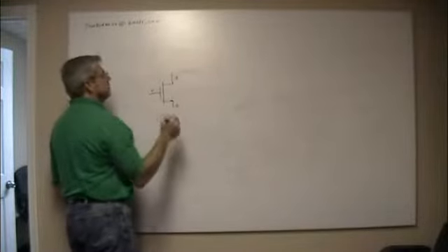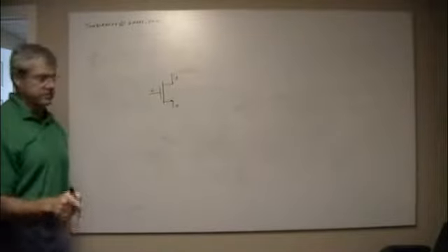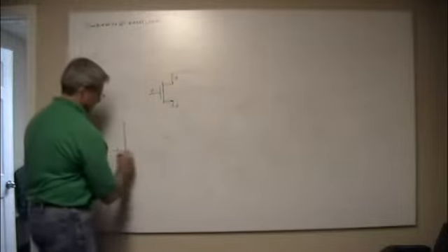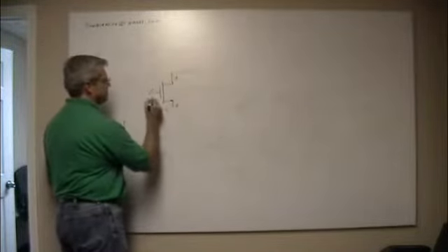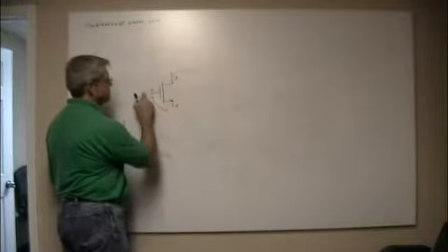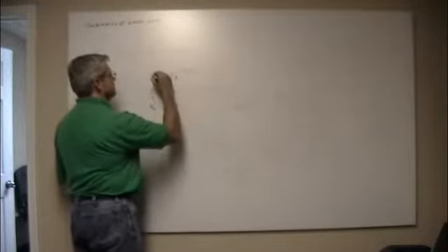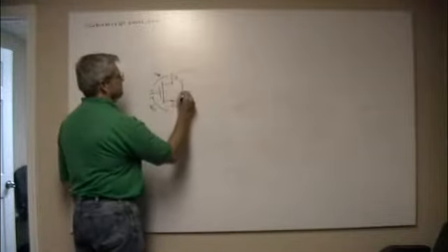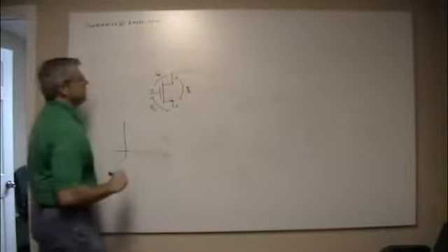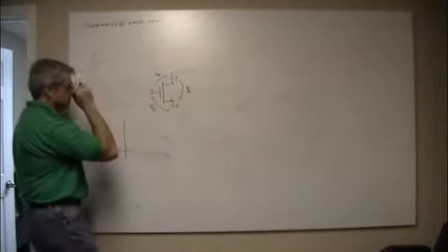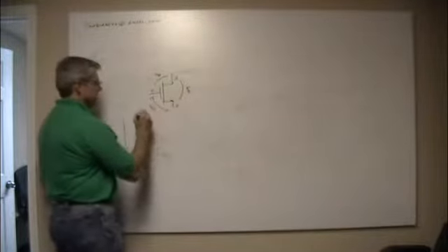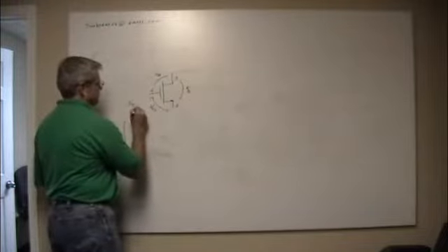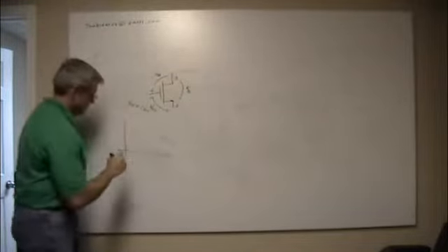And in the logic that we see in our computers, basically what happens is this voltage level here is VGS, gate to source. This is V drain to source, and this is VDS. And I'm not going to get into the math in these, but there is what they call VT, which is the so-called turn-on voltage. We'll say it's 1.2 volts just for S and Gs right now.